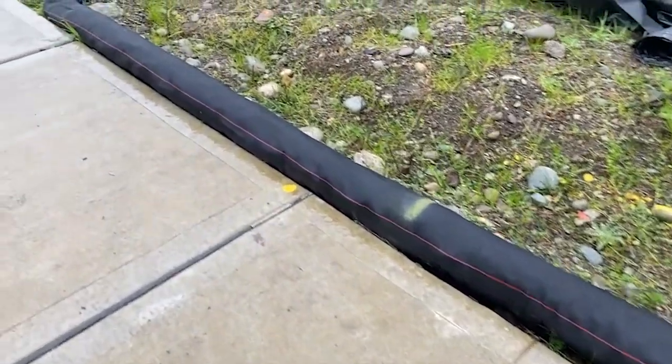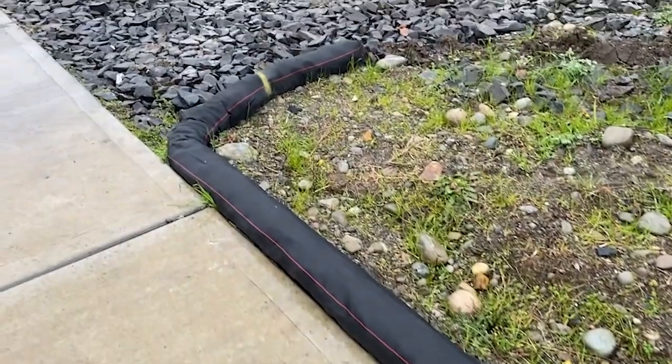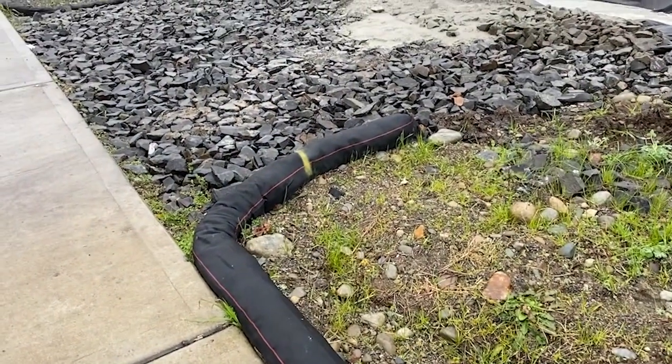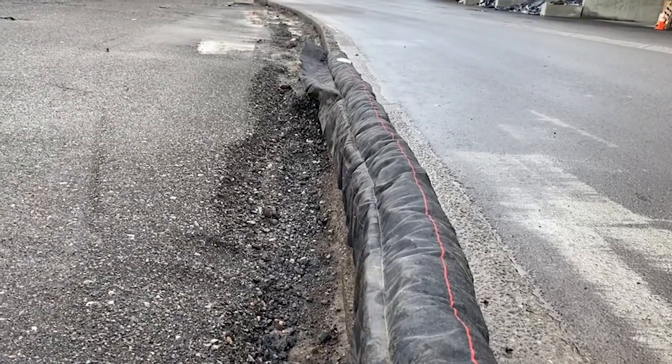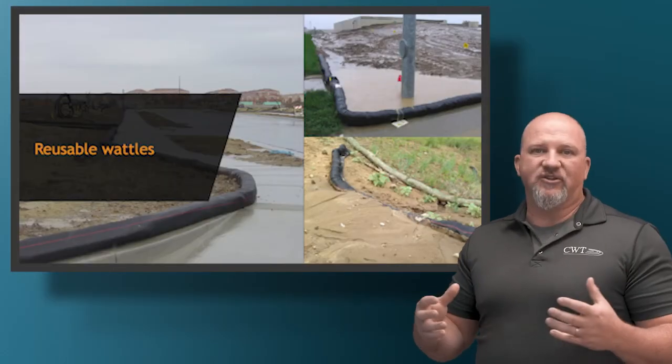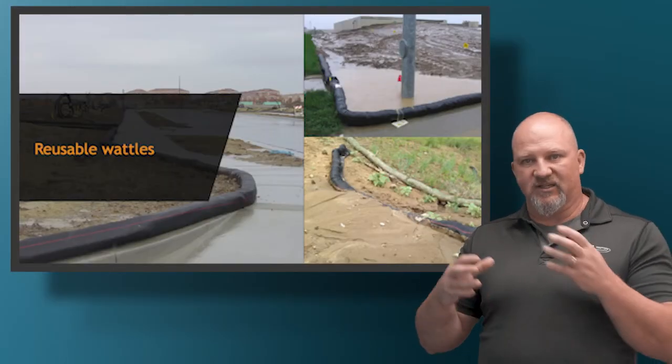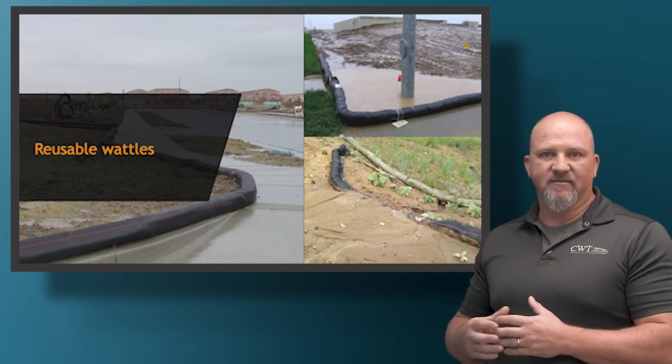They stay above the ground, they're reusable, they can go from project to project. They can also be applied on hard surfaces. They're good for concrete cuts or areas where you can't trench into the asphalt subgrade to get the straw wattle or silt fence in there.